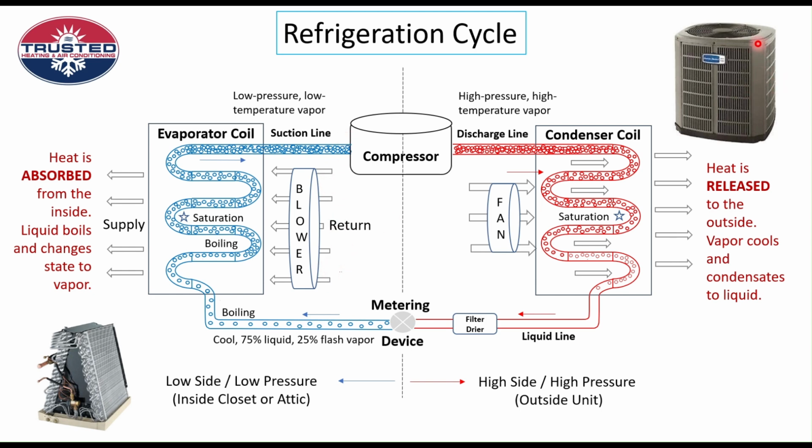Along with that, on the outside, the air is pulling across and through these fins and these tubes, and it's important that this unit is kept clean. As a homeowner, you could spray this down from the top to the bottom and remove the dirt and maybe cottonwood and dust and things like that, so that this unit is able to breathe and circulate air across it to reject heat and operate more effectively and efficiently, and with less electric bill as well.